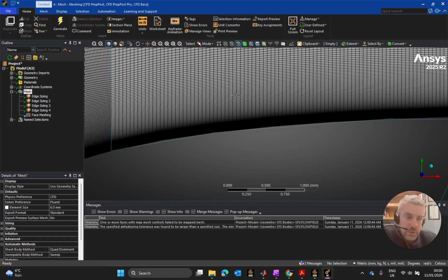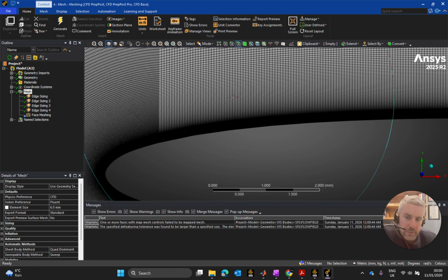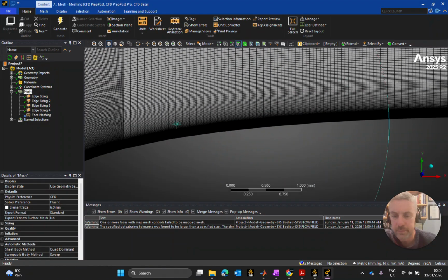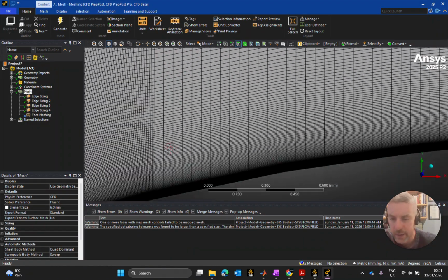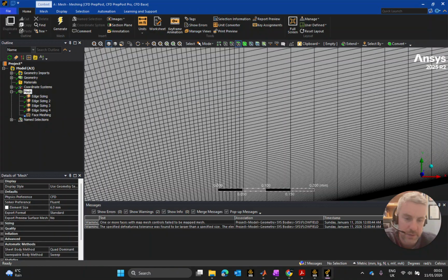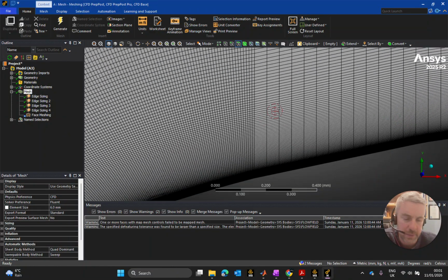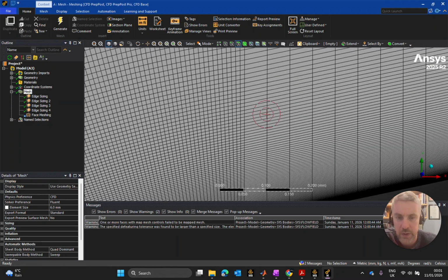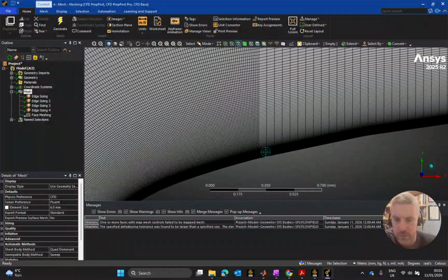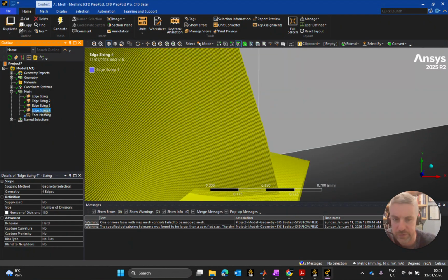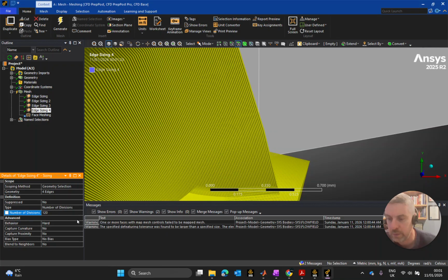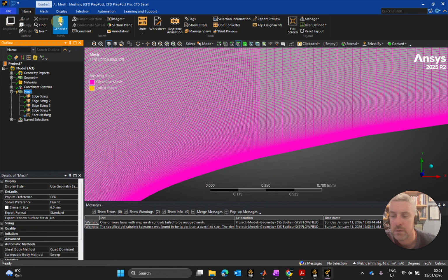So what we're going to do in videos after this is run the mesh independent study and create a mesh that has twice the elements and a mesh that has half the elements, and we're just going to keep resolving there until we get a fairly good looking mesh. This front one here, what I might do is reduce the amount of divisions on this front one. I have that up to 180. I bring that down maybe to 120. See how we go.